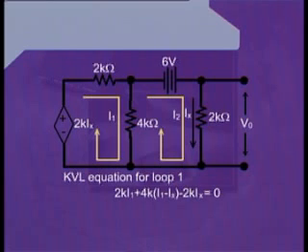After writing this term, we reach the bottom node of the 4 kilo ohm resistance. From there, we can see the current dependent voltage source, which has a value of 2K Ix. However, we can see a negative sign while looking at the voltage source. Therefore, we will write minus 2K Ix. And after writing this term, we reach the starting point. Therefore, we write equal to 0.